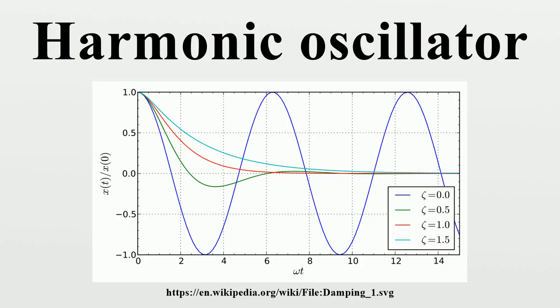Amplitude part. Squaring both equations and adding them together gives, therefore. Compare this result with the theory section on resonance, as well as the magnitude part of the RLC circuit. This amplitude function is particularly important in the analysis and understanding of the frequency response of second-order systems. Phase part. To solve for phi, divide both equations to get. This phase function is particularly important in the analysis and understanding of the frequency response of second-order systems.